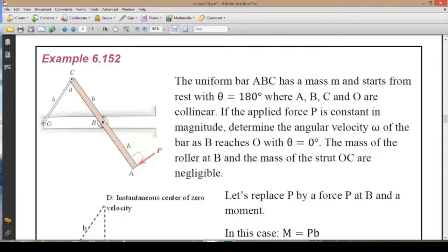We have a revolute joint at point O, another revolute joint at point C, another revolute joint at point B, and then there's this linear action. We have this force acting relative to the coupler link by 90 degrees, so it is always at 90 degrees orientation with respect to this link. And the linkage starts its motion when it is aligned along this horizontal line.